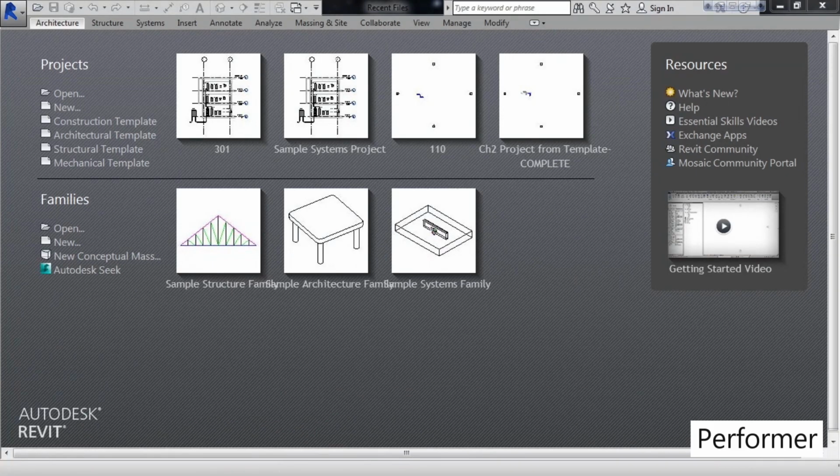For example, in an office, you may have multiple disciplines working on a Revit file. Architecture, doing the walls, doors, windows. MEP, the mechanical systems, mechanical, electrical, and plumbing, and maybe also structural engineers, creating various structural elements, columns, beams, steel girders, if you will, within that Revit model. Now, two ways to handle that would be work sharing, where people are collaborating on that one actual model itself. So all of those disciplines add their designs, create their elements, and then it's collaborated or shared through work sharing.